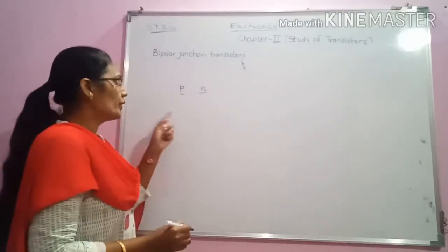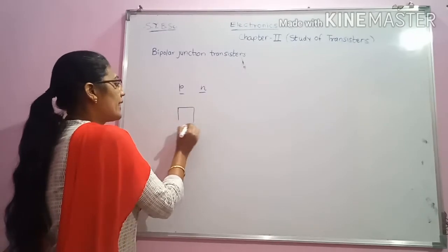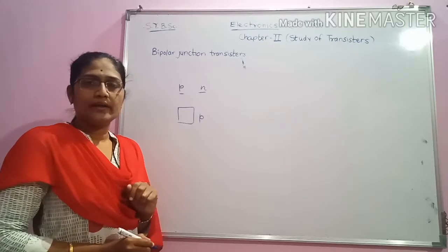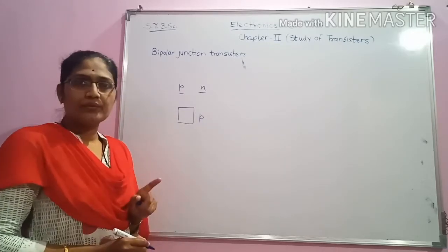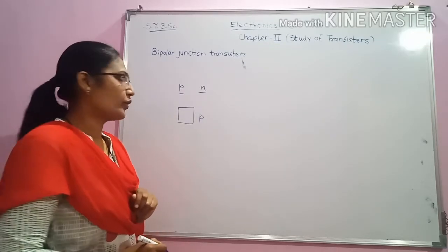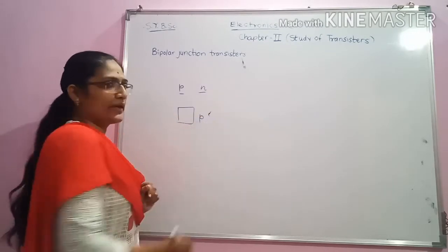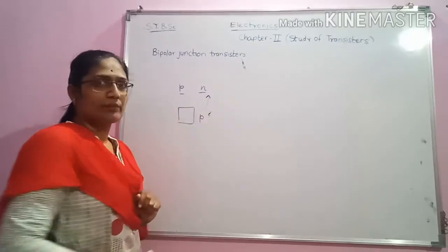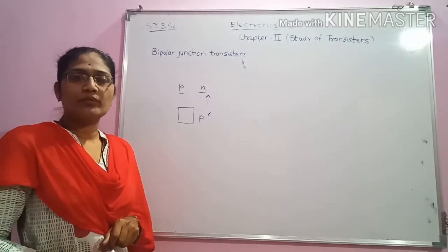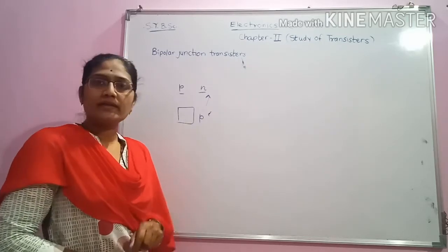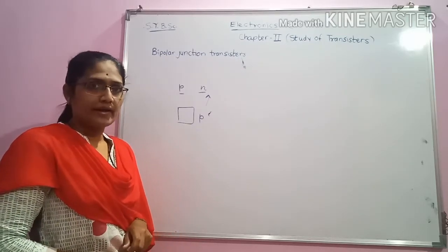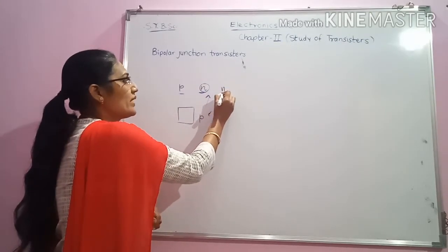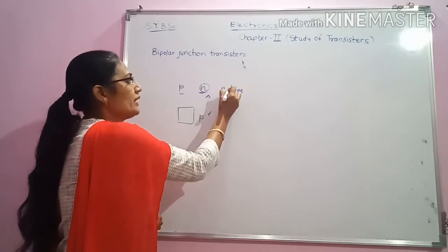When we consider a pure element and add a pentavalent impurity to it, that is, an element which has 5 electrons in its outermost orbit, there will be an excess of electrons, and this will give rise to N-type semiconductors. These semiconducting materials consist of an excess of electrons, meaning negativity, hence they are named N-type semiconducting materials.